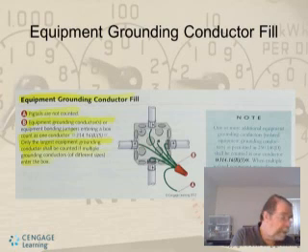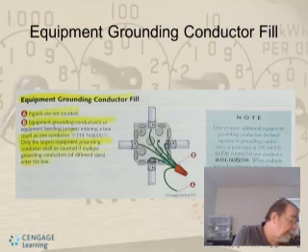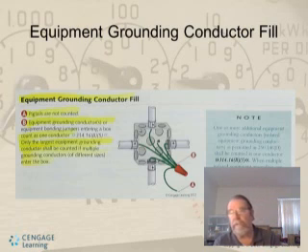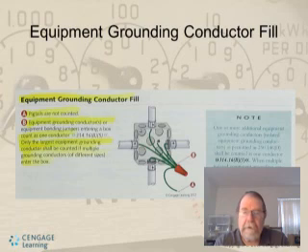But conductor B is your equipment grounding conductor, and only the largest equipment grounding conductor shall be counted. Usually that one's a gauge or two larger in size than the ones coming in. Say they're all 12 gauge, and so you may have a 10 gauge that's connected in there as you're coming out.